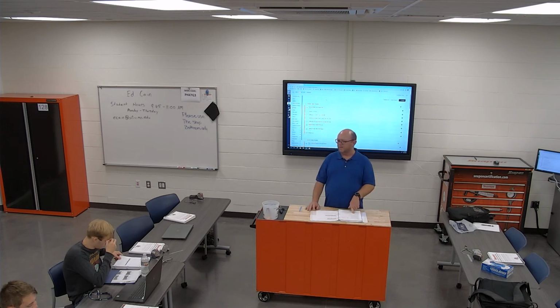So our shell mill's got what, 5 or 6? It's 5. So you would take it times RPM times the 7 thousandths times 5, and that gives you your inches per minute. Follow?